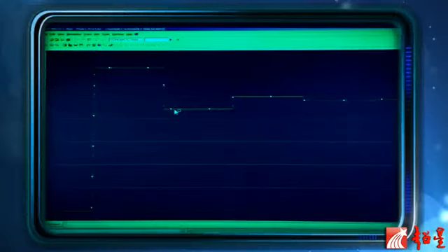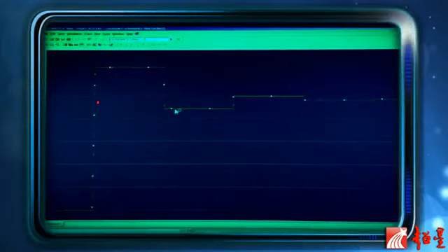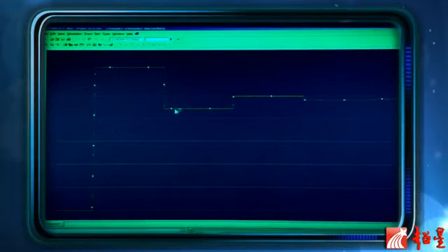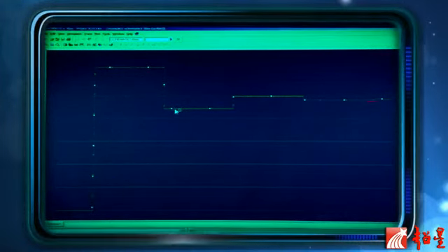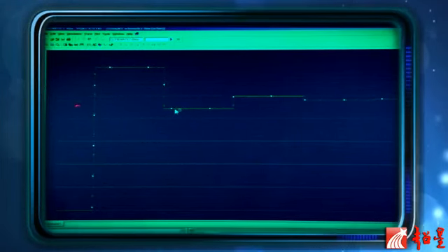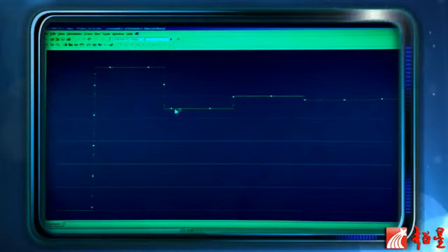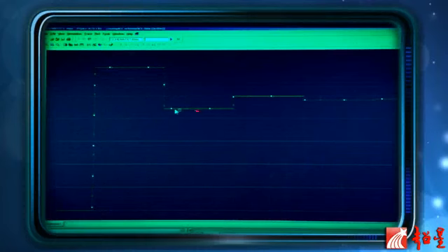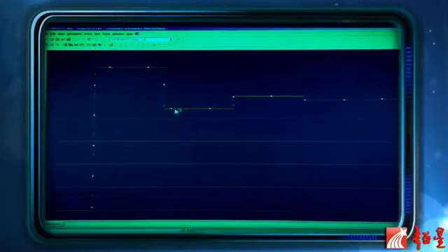This is a SPICE simulation. It's a bit hard to read. You can see that it reaches a steady state here, and then there's oscillation. That's called ringing. We can actually display voltage values at some of these points. Let me show you how to do this.